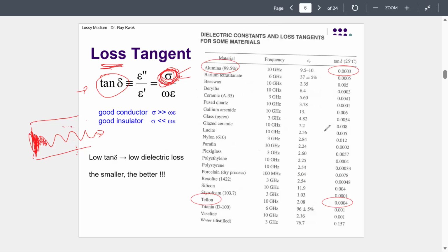But remember, when I have a printed circuit, a PC board, with a circuit on top, this is the trace. Where is the energy of the signal? We talked about that before. Where is the energy stored? Is that on the trace? No. Faraday's law tells me the magnetic field is going around the wire. The energy is in the material, in the dielectric material.